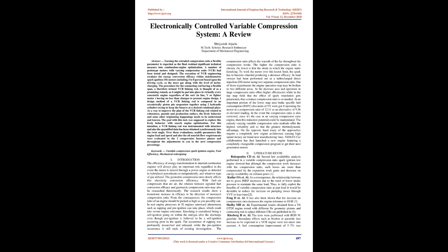In real engine processes in SI engines, undesirable phenomena such as knocking and pre-ignition can take place, which result in severe engine damage. Knocking is considered to be a self-ignition occurring within the end gas after the spark, whereas pre-ignition is believed to be a self-ignition occurring prior to the spark. The occurrence of knocking was extensively researched and published, while the pre-ignition phenomenon is still a topic of current investigation.